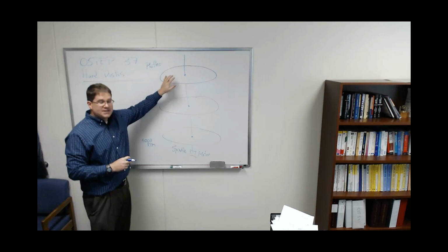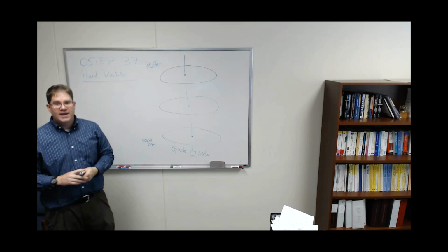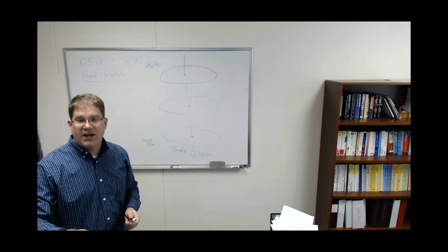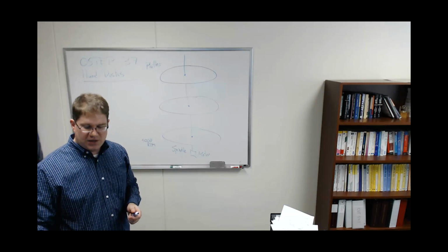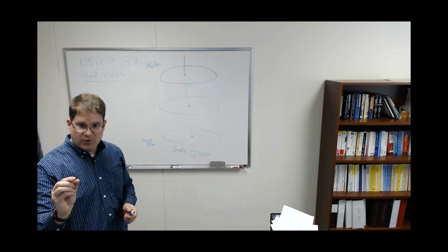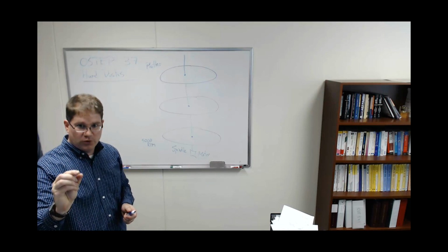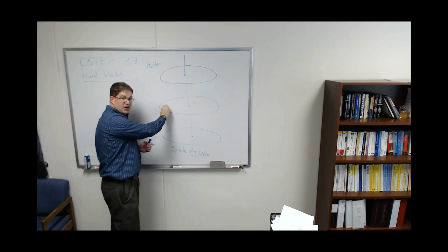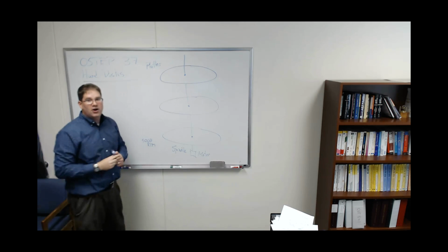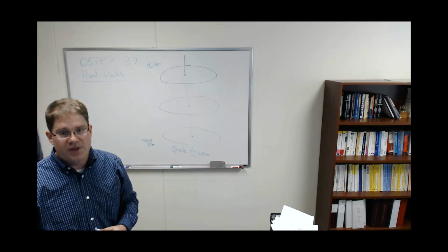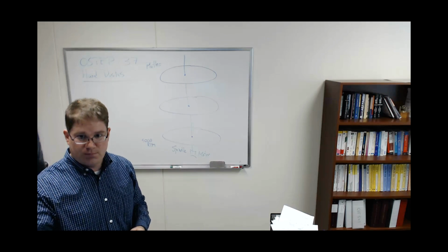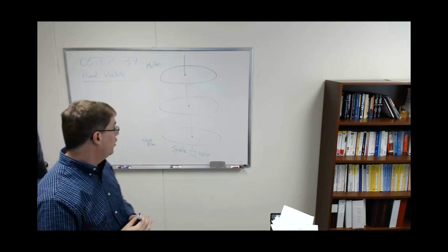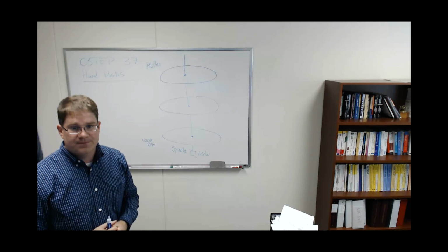Now, each one of these devices is a steel platter that's been coated with a nice polished surface, and it is magnetizable, meaning that if you take what's known as a little read-write head, a little magnetic ferrule, that you put right on the platter and run a little current through it, by creating a magnetic field, you can make a little spot on that disk in which the magnetic orientation of the molecules are either pointing all up or pointing all down. And so that can represent either a 1 or a 0 at any little position on that disk.